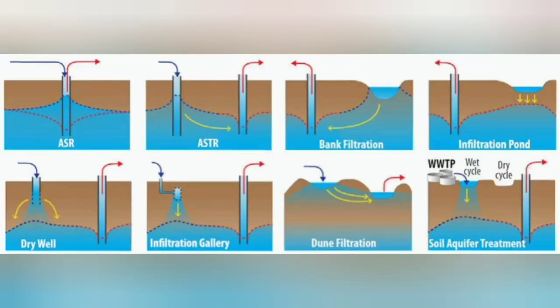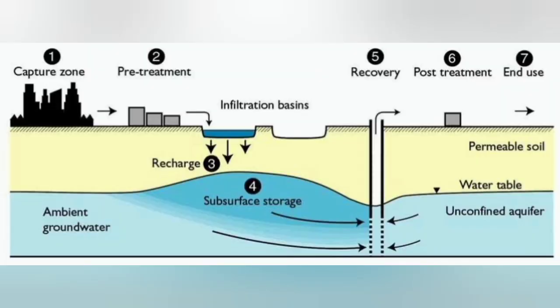The vegetal cover increases infiltration as compared with barren soil because it retards the surface flow, giving the water additional time to enter the soil. The root system makes the soil more pervious, and the foliage shields the soil from raindrop impact and reduces rain packing of subsurface soils.